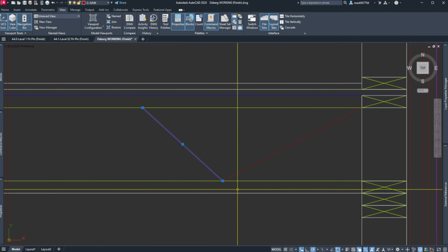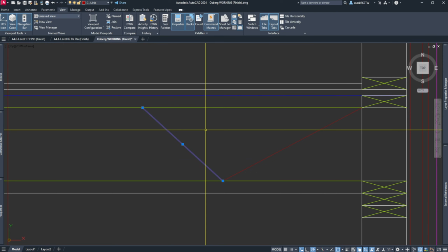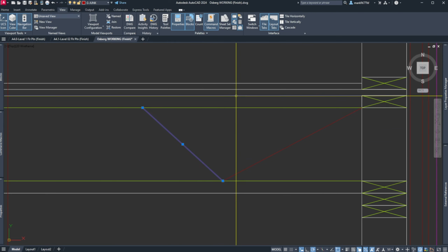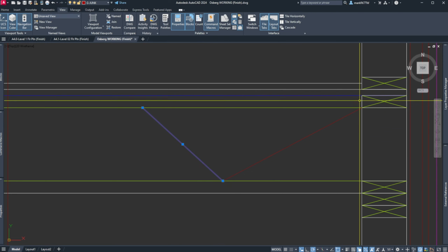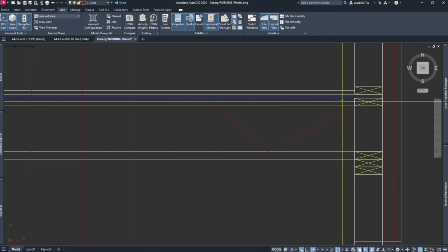It's just webbing in here. Of course, it'd be thick. Then above that, I've got my subfloor, which is 3/4 of an inch. And then I build my wall on top of that. And then I've got another 3/4 of an inch for a total of 1.5 inches to have any sort of finished floor,